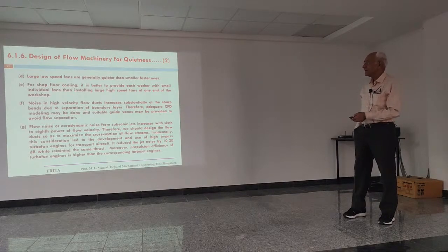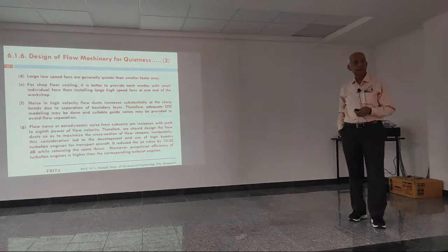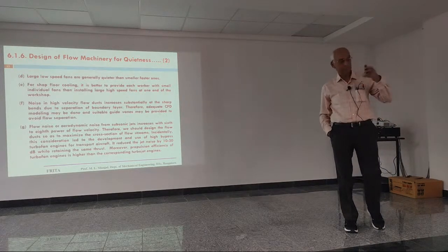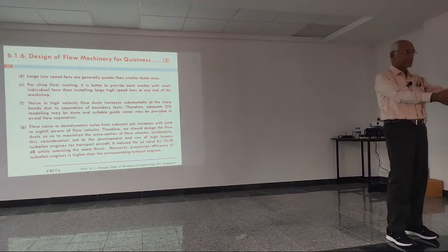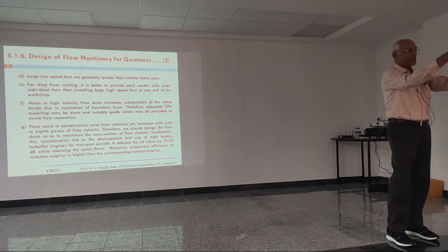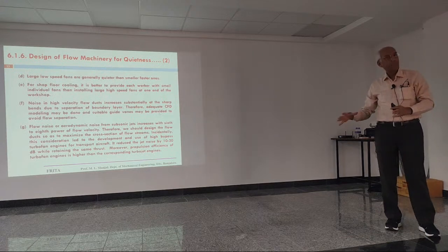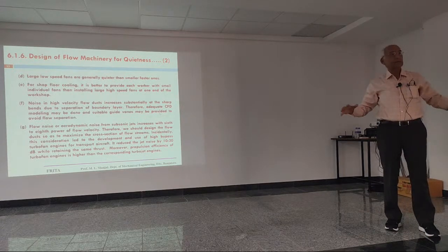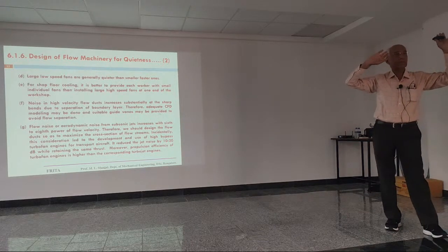Continuing that, large, low-speed fans are generally quieter than smaller, faster ones. Now, this is something that I want to stress here. Often you go to these factories, you have, for example, a number of layers in one row. People are working on that, and then what the management does is put a big fan here, giving air and thinking that everybody will be taken care of.